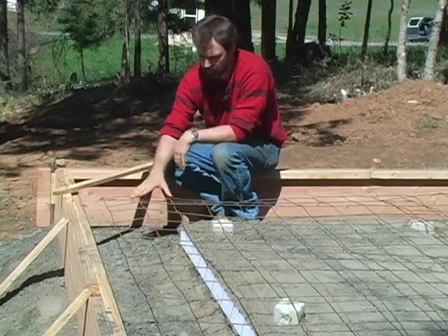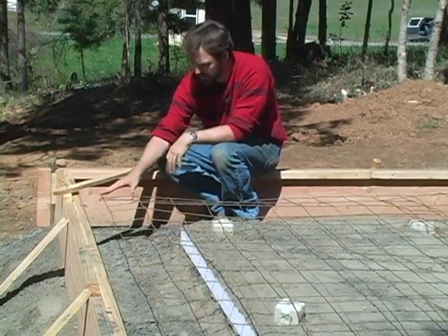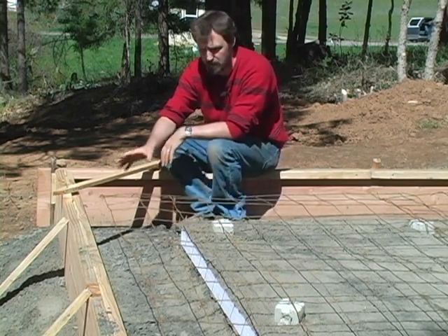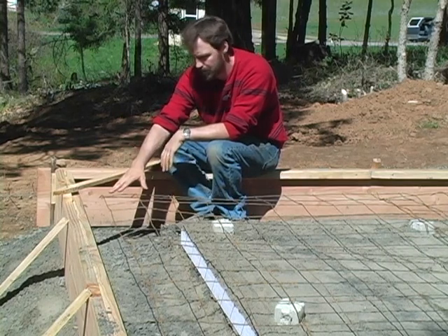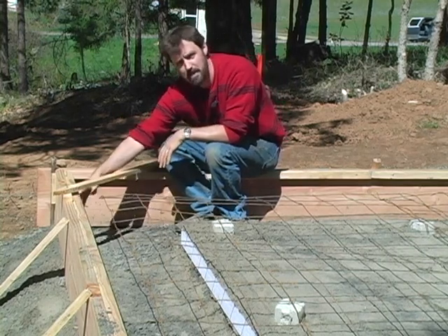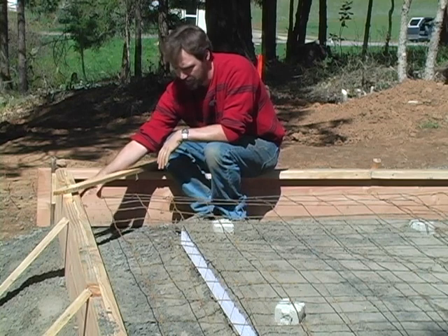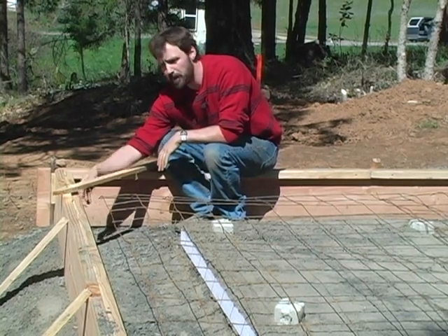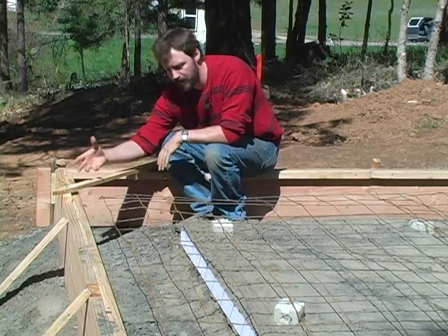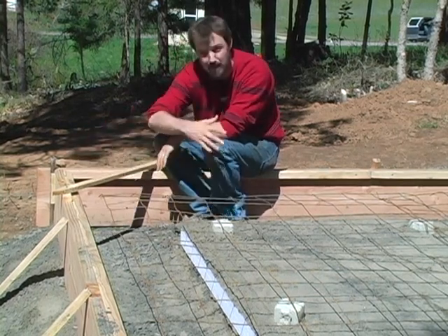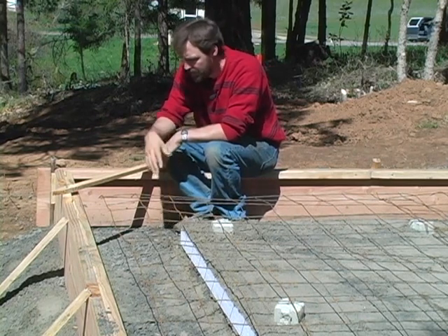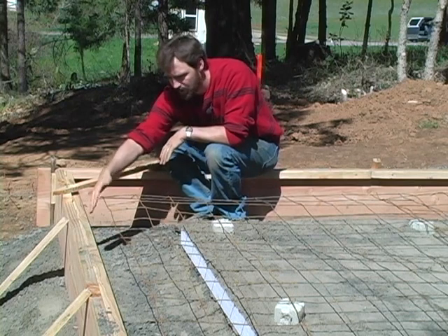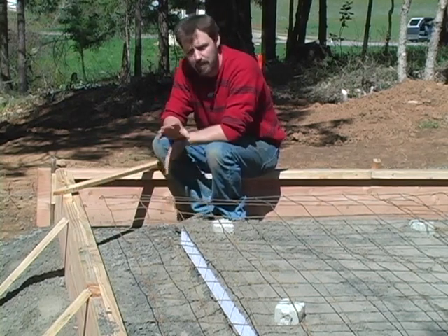Whether you use the welded wire mesh or rebar, you need to be sure to keep it away from the edge of the form boards. Local codes will have certain restrictions about how close to the edge of concrete you're allowed to get with your steel. I like to keep mine about 6 inches in from the form board. The reasoning behind this is if it gets closer or actually touches the outside of the form board, then you're going to get moisture affecting it and rusting it out, and then it'll start to travel down the steel and decay all of the steel down that run. So if you keep a good 6 inches between the inside of your forms and the outside of your wire, that's a good safe distance.